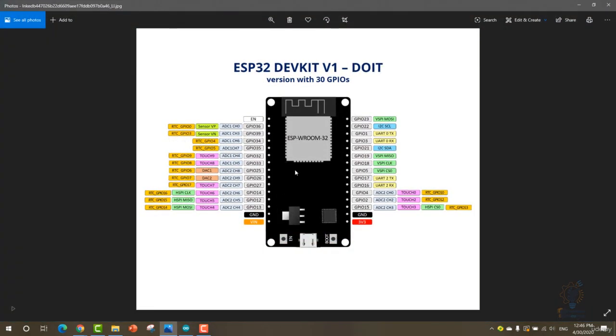Hello and welcome. In this lesson, we are going to take on the PWM pins of the ESP board. All 36 of the ESP32 general purpose input-output pins have a PWM capability. This is a really great thing, but we must use more complex code to reach the same result on other pins.